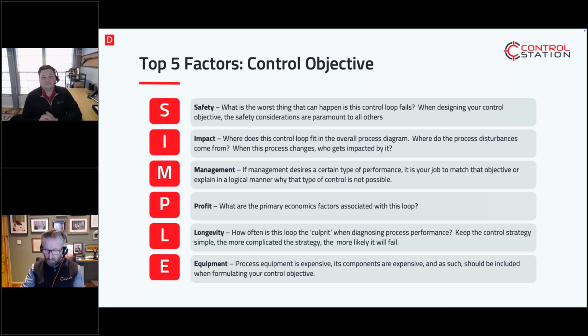I suppose, sorry to jump back in, but that control objective, it's hard work initially, but it starts to pay off in that you can set your control objective for flow controllers, for temperature controllers, so that you can approach it with this standardized methodology. So every flow controller can be set like this, every temperature, so you can start to build this template almost for how you approach them, but it's the documentation that does it, absolutely. Documentation allows repeatability, right?